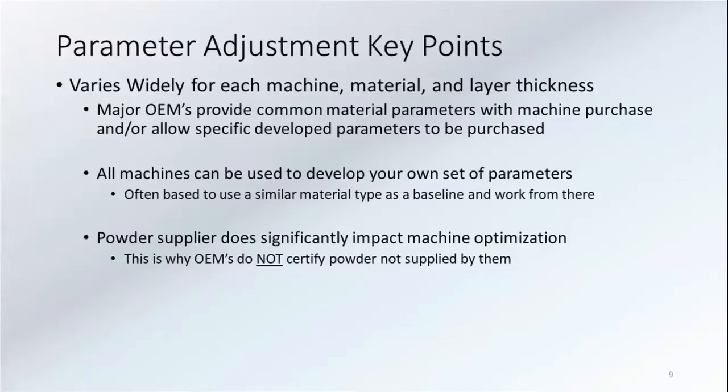Now, nothing is saying you can't just tweak it. You can buy the other large powder line. If you're doing lots of builds, get a good reputable powder supplier. And if you want to certify it yourself, by all means, please do that. You can save a lot of money that way, but you will be doing a couple weeks of studies, if not a couple months of studies, to get this honed in a little bit. But you can start with a lot of things that are out there. So if you're doing aluminum, you already know where you're starting. Laser parameter-wise, you're just tweaking it.